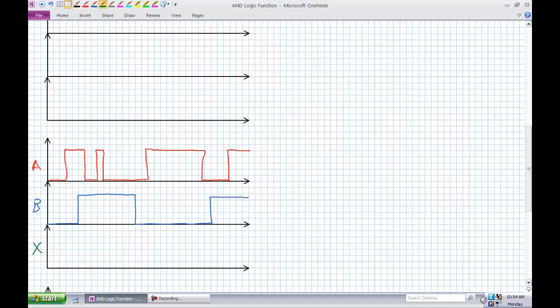An AND gate, the output is high only when all inputs are high. So I can shortcut a lot of these things. You can do that whole walking from time 0 to the end of time, but it's far easier to just use that expression. Its output is high only when all inputs are high.